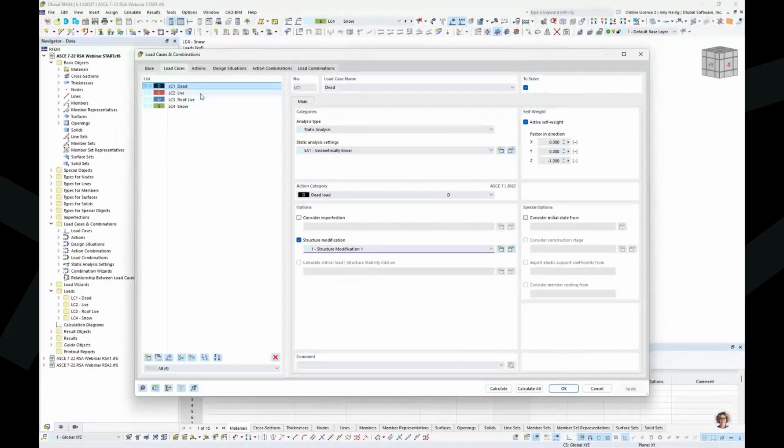So now that we have our 4 static load cases here, I'm actually going to make a copy of my existing dead load case. And the reason why I want to make a copy of this is I want all of the loads that have already been applied under the dead load case to also be applied here in load case number 5. This is going to have a new load case name here for our vertical seismic. And I'm not quite yet ready to jump into the response spectrum analysis, but I am going to apply the seismic loads as a static load type to begin with. So therefore, we can rename this one to vertical seismic.